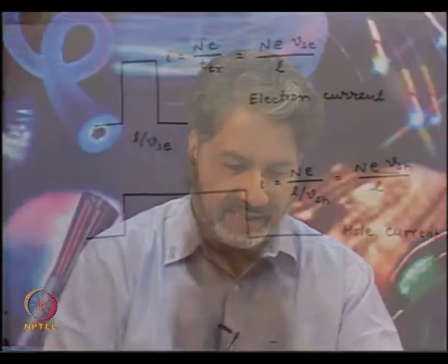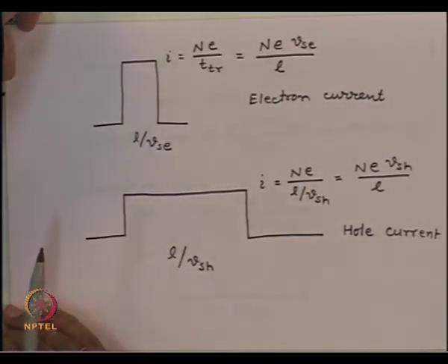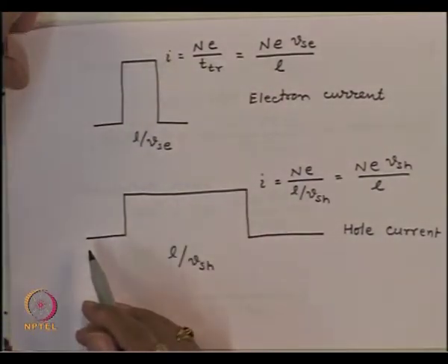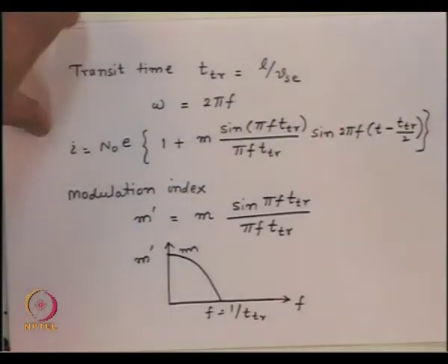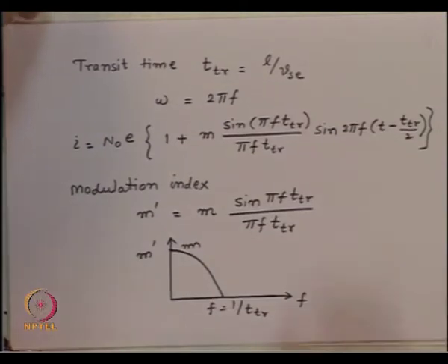That means every impulse is broadened by a rectangular function of width equal to the transit time. So, the impulse response for this device is nothing but a rectangular pulse, which is the current shape shown earlier. Therefore, the frequency response will be the Fourier transform of this function, and thus the quantity we have got from this analysis.